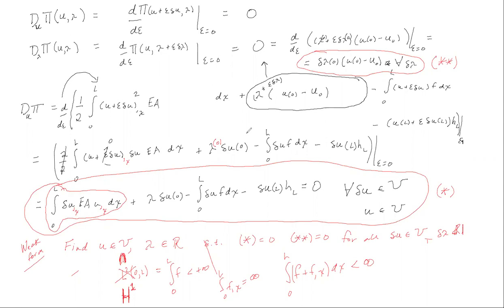When I write down the strong form, every engineer that's listening to me is going to be like, oh, that's what I learned in my introductory mechanics of materials course. But you can't discern that just by looking at these integral equations. And so what happens in finite elements, and that's very important, is that if you postulate a weak form and it has maybe some extra terms that are enforcing this or that, it's good practice to always derive the strong form corresponding to the weak form so that you know exactly what equations you're solving.